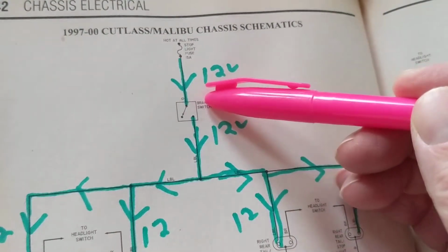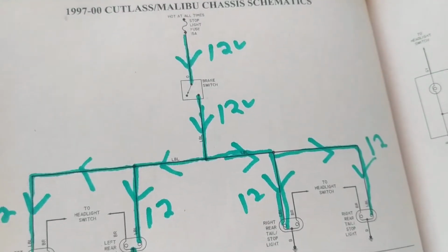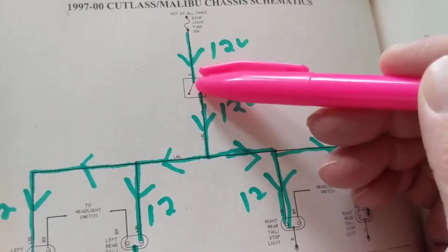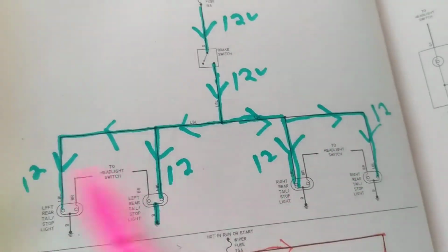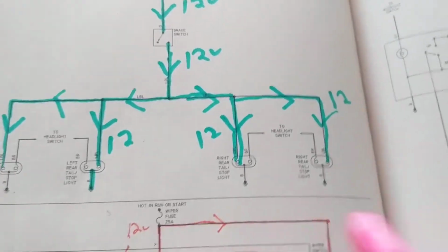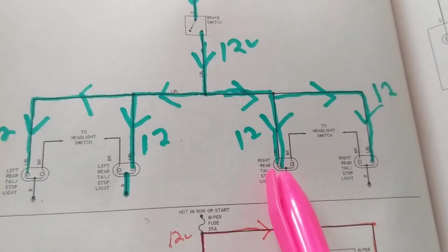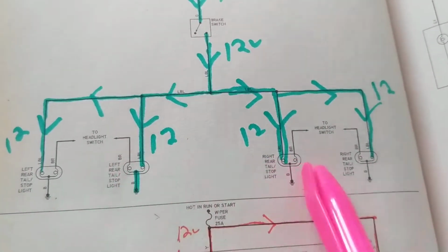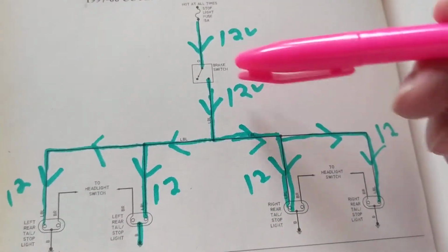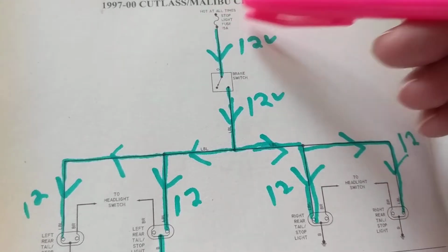It could either be the switch or the fuse, right? If this switch is not active, it's in this position, there's no connection. Therefore, there's no current flowing here, no 12 volts. No reason to go to the connector of each one and measure it if all of them are not lit. You know right away from this schematic, from interpreting it, it's either this or this.